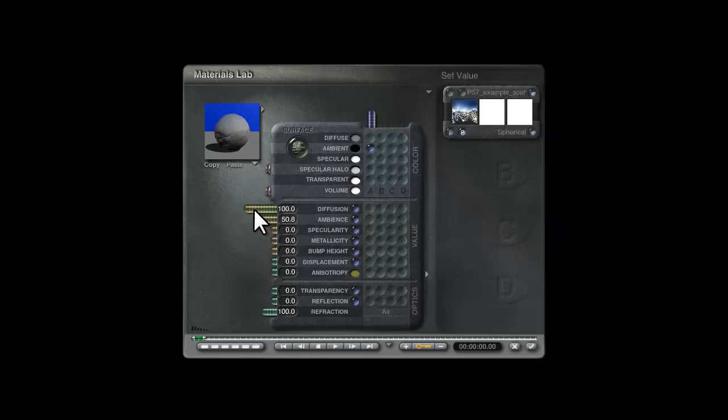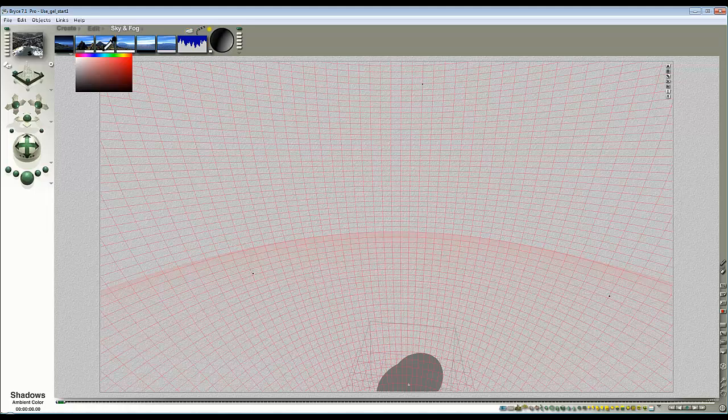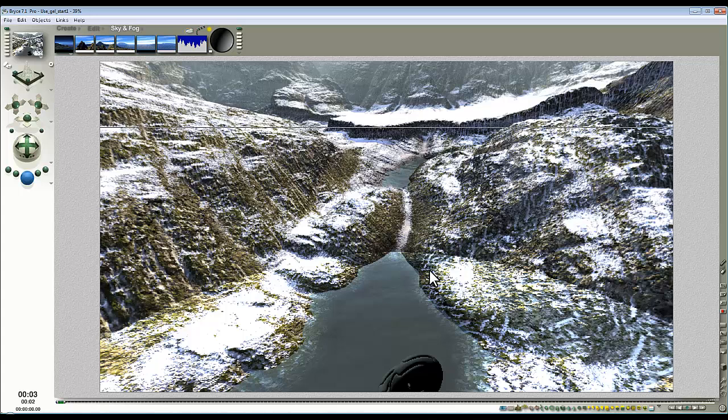We'll need some output in the ambient so you can see what's happening. So there you go, that's its spherical map. Oh, and I can also set it to parametric, which moves it around 90 degrees. Because the mapping mode on the light source was parametric, it seems appropriate to choose parametric for this. So I'll check out of here now and use the global ambient colour to drive that effect. And you can see now they've lined up.